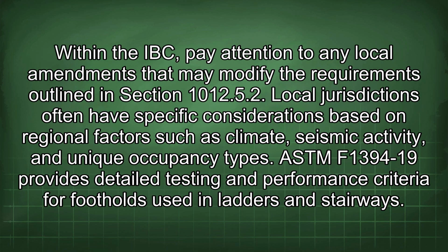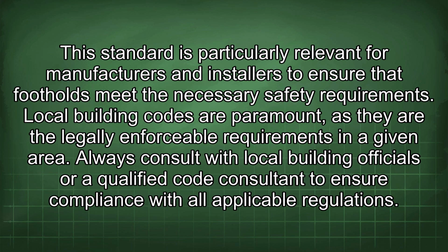Within the IBC, pay attention to any local amendments that may modify the requirements outlined in Section 1012.5.2. Local jurisdictions often have specific considerations based on regional factors such as climate, seismic activity, and unique occupancy types. ASTM F1394-19 provides detailed testing and performance criteria for footholds used in ladders and stairways. This standard is particularly relevant for manufacturers and installers to ensure that footholds meet the necessary safety requirements.